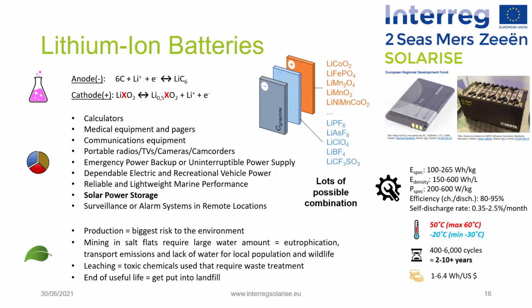The most common negative electrode used commercially is graphite. And for the positive electrode, it is generally one of the listed materials here in orange, like a layered oxide, such as lithium cobalt oxide, a polyanion, such as lithium iron phosphate, or a spinel, such as lithium manganese oxide. And recently, graphene-containing electrodes based on 2D and 3D graphene structures have also been used as electrode components for lithium-ion batteries. The electrolyte is typically a mixture of organic carbonates containing lithium-ion complexes.